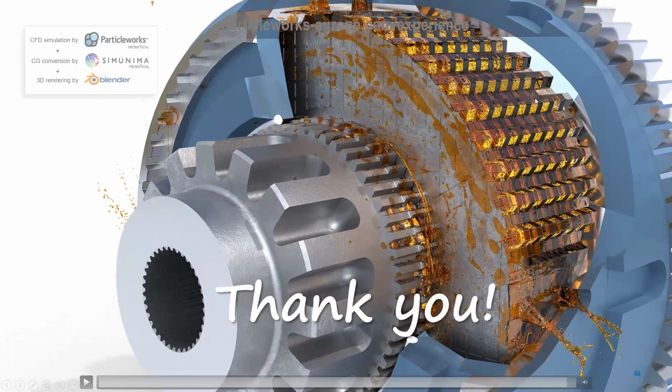So let's see the questions. The first question is, what is the difference between smoothed particle hydrodynamics, like Preon Lab, and moving particle simulation? They are both particle-based methods. Moving particle simulation is for incompressible fluid, while SPH is for compressible fluid. And I can tell that as compared to SPH, the stability conditions for moving particle simulation are actually less demanding. So we are looking at usually faster simulation times.